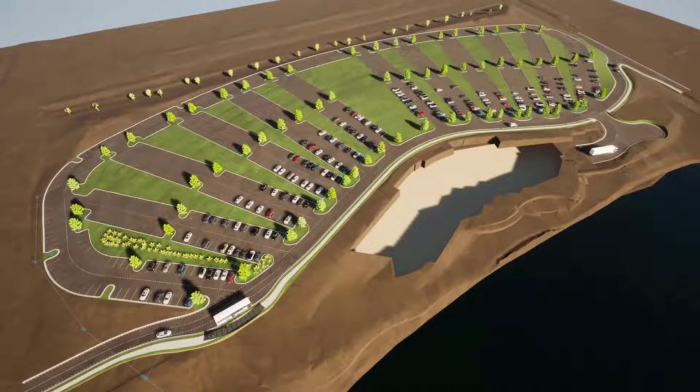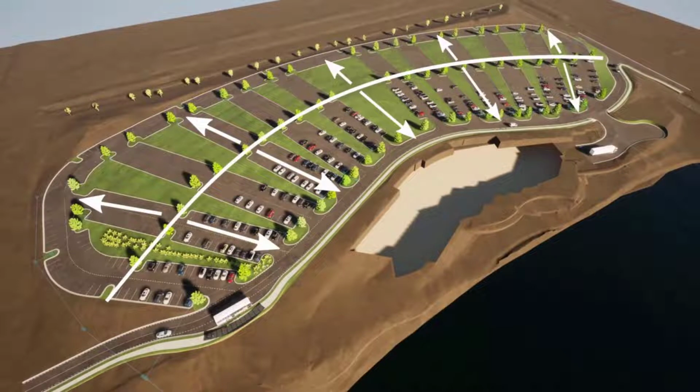The last point before we start is that everything here is based off the drainage of the car park. The system we've employed for this is a tilted plane grading object, and the crest of that plane is the solid white line, and it flows where the arrows are going. So the drainage will go to both ends of the car park based off that, and then we can put in a whole series of pipes to capture this. As we're designing our main road and our outer circuit road, we will reference that grading plane and make sure that they tie in with that object.